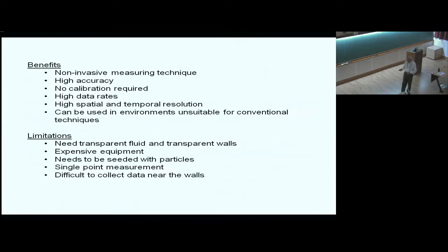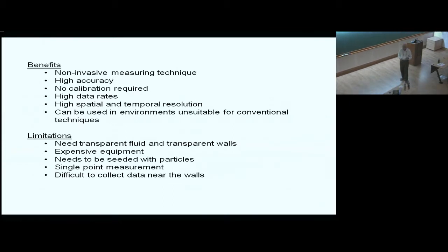Of course, the limitation is that both the fluid and the wall need to be transparent. And it is relatively expensive because of the laser and the optics itself, the analysis. But actually, if one has the motivation to build one, then it turns out to be relatively inexpensive, except for the laser, and lasers nowadays are quite cheap. The electronics itself is not that difficult to build. And one problem, of course, arises in this technique. If you go very close to the walls, then you have problems with reflection.